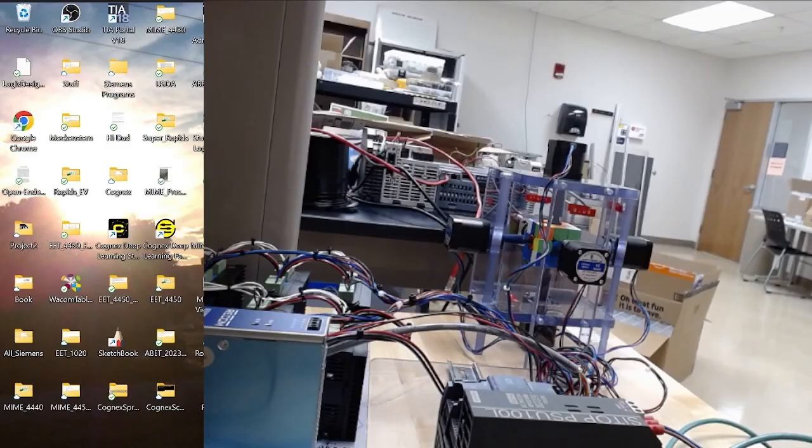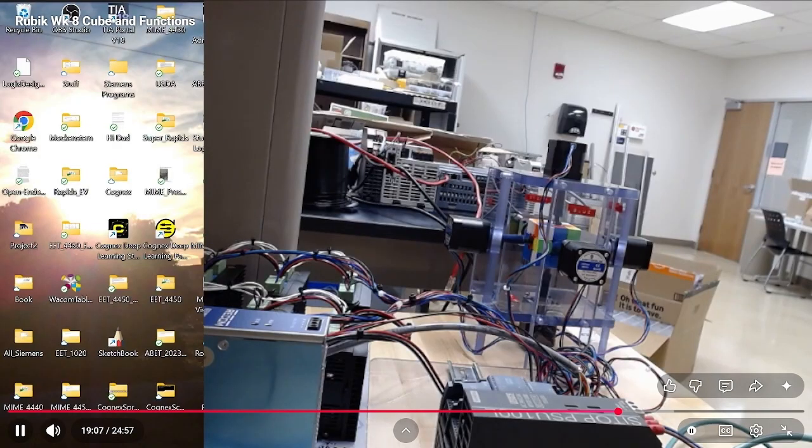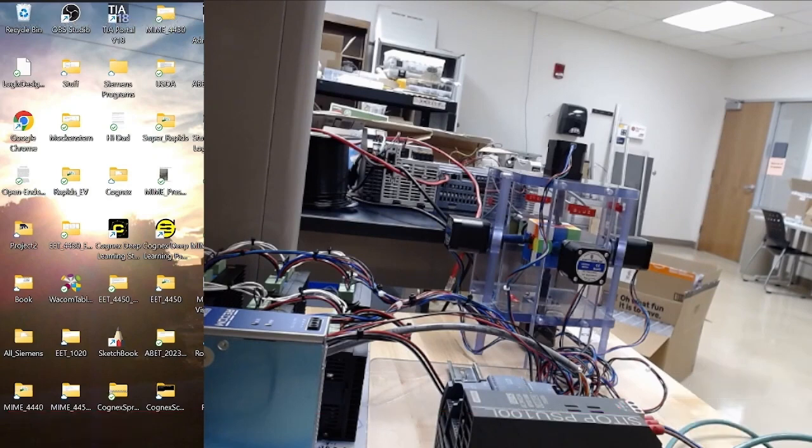So you put the minus in front of it, you click enter, and then you say move, and it'll see if it moves, and it does move pretty well. For the most part, it works pretty well. Occasionally it's a little sticky, but again, you're going to have to work on details. There is no feedback with these, so you don't have any way of knowing if they don't go quite that way. Before you get started, you have to make sure that these are going at 90 degree spins. So now you've got a way of moving both positive and negative, either 90 degrees or 180 degrees in either direction, and the positive direction is clockwise, the negative direction is counterclockwise.